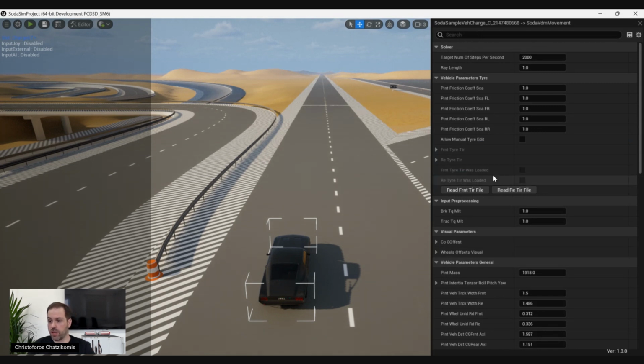And we also have our vehicle dynamics model that is very precise and fully parameterizable. We can change all the parameters that we would like, so we can match the behavior of our target vehicle. So we can change things like the friction coefficient of each tire, also load, the tire parameter, for example, that we have for a magic formula tire model.